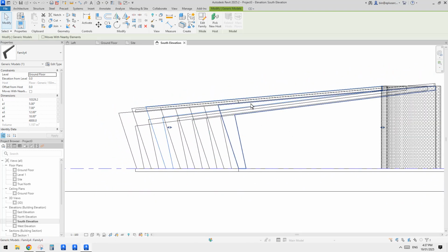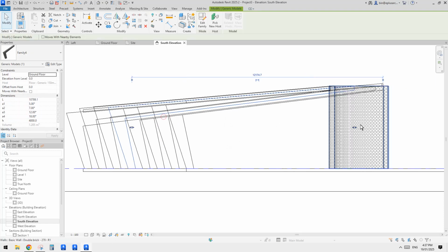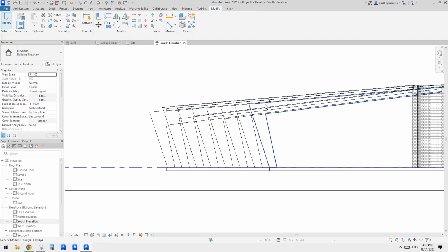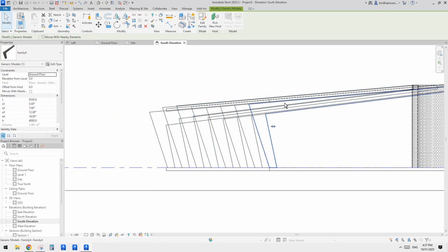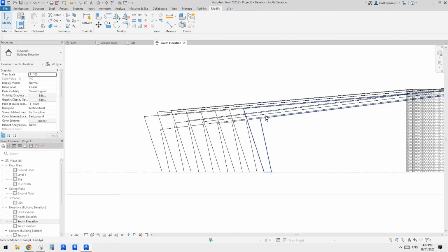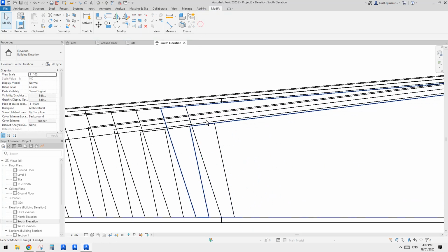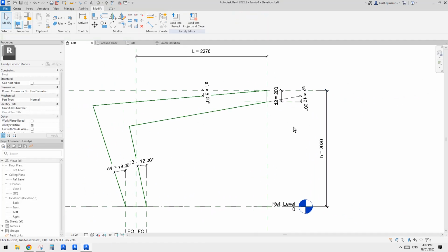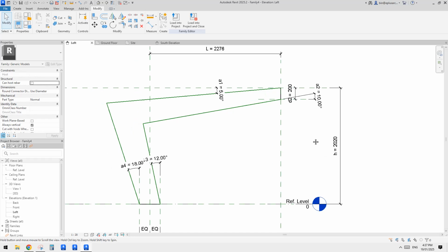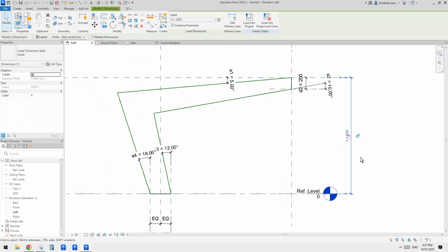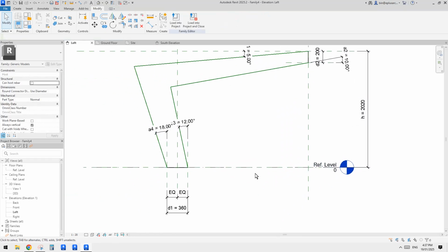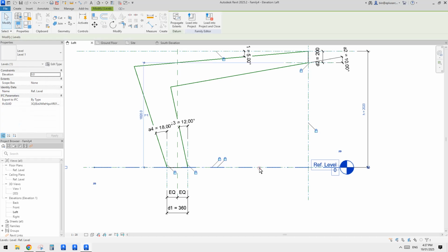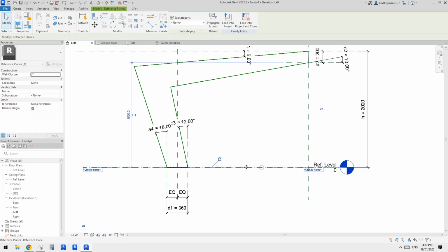Do we have an option to just drag this one, but on this height? Yes we can. So now let's go to family. We have this instance parameter, but we don't have that handle. Why is that? The reason is, when we do a dimension, we dimension onto a reference level instead of a reference plane. So you can see there are two elements here. One is the reference level, one is the reference plane.